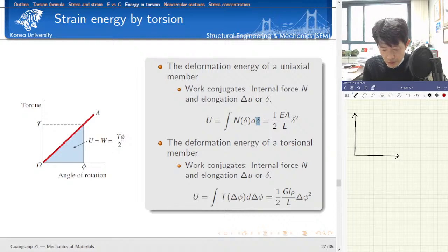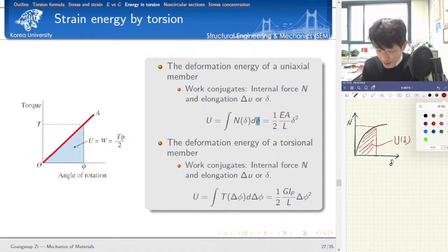Let's use nonlinear behavior and elongation. In the case of nonlinear materials, it would behave like this, isn't it right? If you calculate the deformation energy, as I told you, the area under this curve is equal to the deformation energy, U, which is given as a function of elongation. And you can calculate the complementary energy, which is defined as the upper part of the load displacement relation.